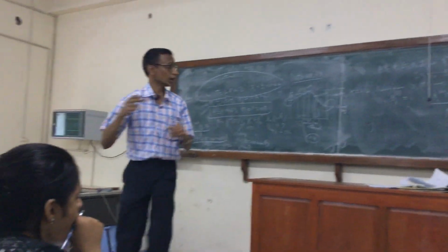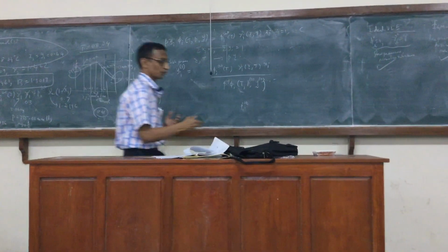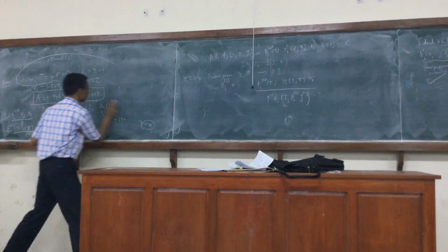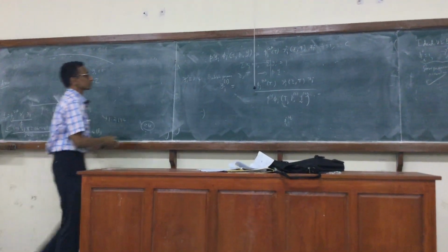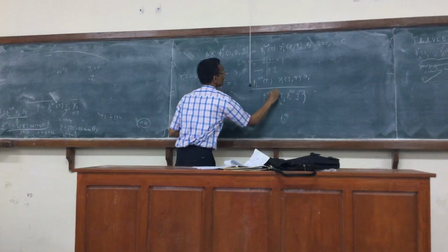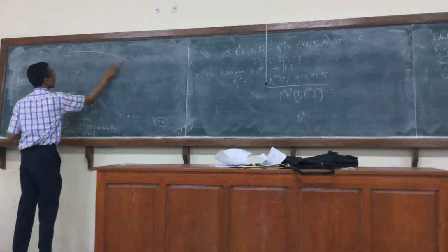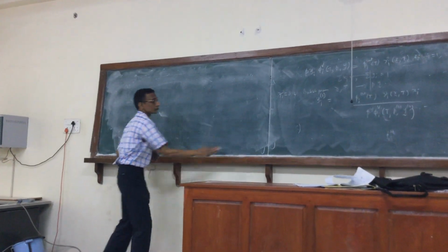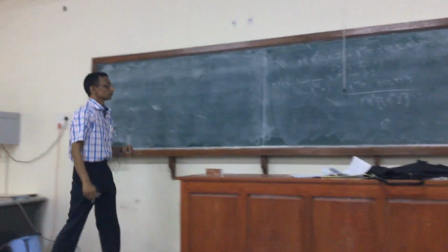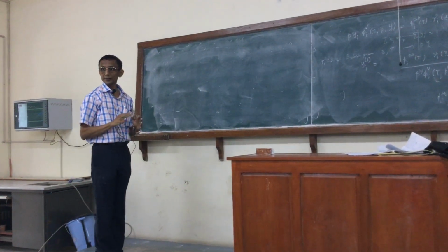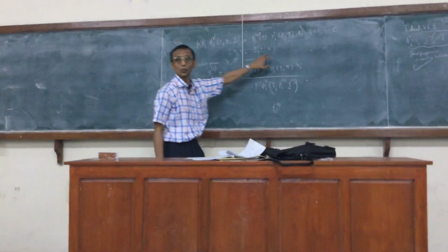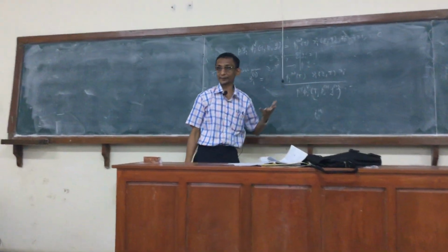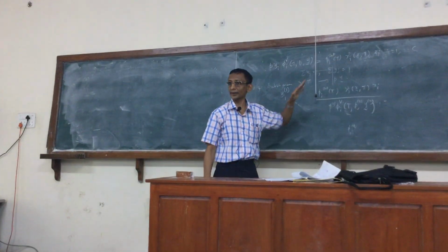But now there are two stages. The only difference between this and the phi approach is the way the gamma is now replaced by the phi of the liquid. So I have to be clear, this is the vapor. Now what are the equations? The procedure is the same. Whichever mole fraction has to be found. So for bubble pressure, it is y, right? So for dew pressure, it will be x. So I have to rewrite this whole equation in terms of xi equal to something.